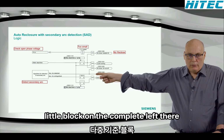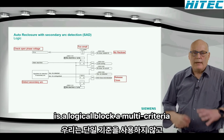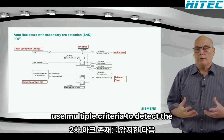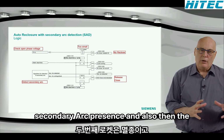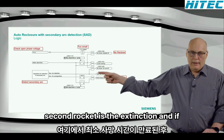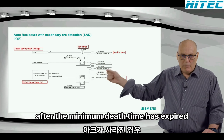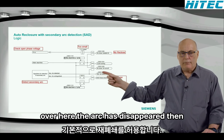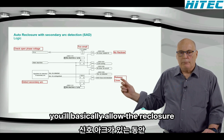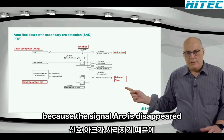And the little block on the complete left there is a logical block, a multi-criteria block. We don't use a single criteria, we use multiple criteria to detect the secondary arc presence and also then the secondary arc extinction. And if after the minimum dead time has expired over here, the arc has disappeared, then you'll basically allow the reclosure because the secondary arc has disappeared.